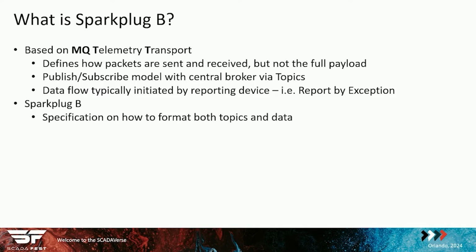And this allows the devices to communicate via a common framework, because the initial issue with MQTT is, yes, you can implement it, but then every device needs to know the same language in order to interpret the data that's coming to it. That's what Sparkplug B has done for MQTT. It has defined the language, that way everybody can talk to each other and understand what they're saying, instead of just sending messages back and forth kind of blindly.